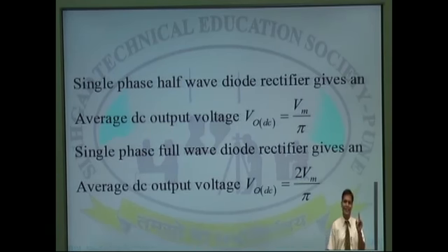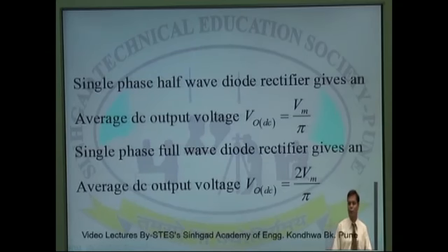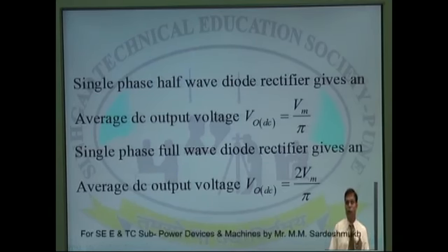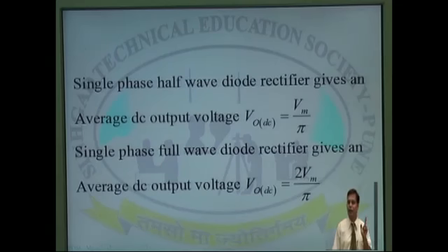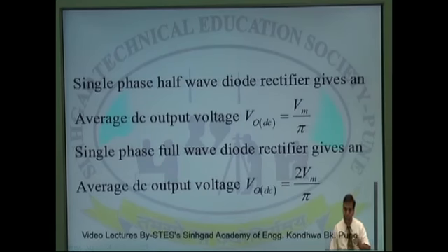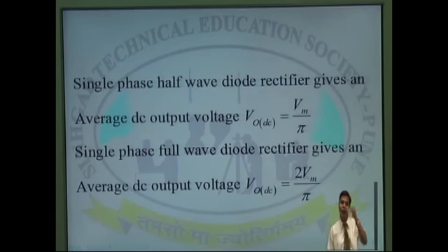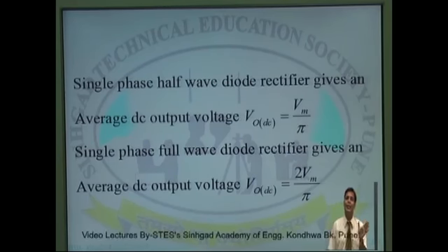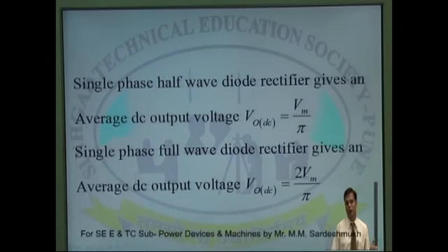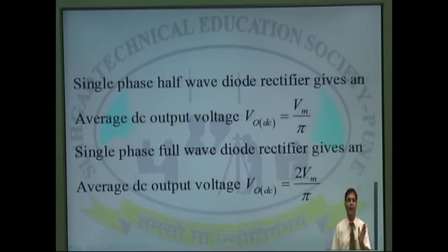Junction J1 will be forward biased and junction J3 will be forward biased, but because of junction J2, current will not flow from anode to cathode and the device will be in the forward blocking state. When we apply the gate signal, then and only then is the device going to turn on, and when to apply the gate signal can be user defined and user controlled. So I can control the firing angle alpha in the case of a silicon controlled rectifier.